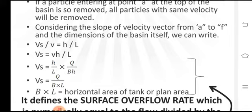So the settling velocity is taken by the depth H, while the horizontal velocity is taken by the length L. So we are comparing both the triangles, so we can write it in this form. By writing this in this form, we are going to simplify this formula in the form of Vs, which will be equal to V into H divided by L.